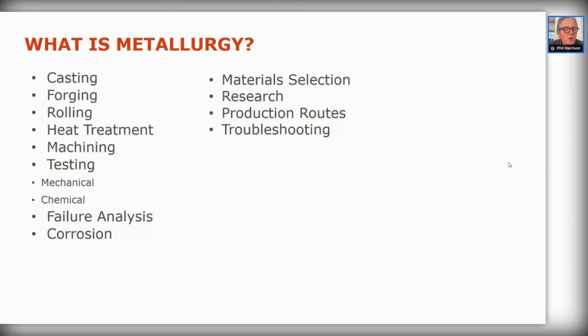The properties of a wrought product compared with a cast product, every single property is improved, whether it be proof stress, tensile strength, fatigue life, elongation, fracture toughness. All properties are increased by hot working. Then, when we've done all this work on it to refine the structure and overcome the cast structure, we have to heat treat it.